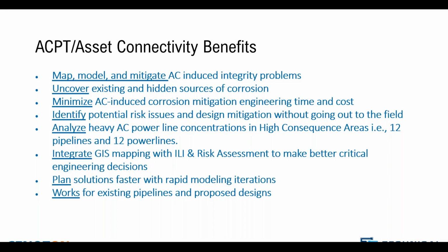The pig run is not infallible. It's fallible because we still have people looking at it, and usually the pitting that you see is small. It's not like large lengths of pitting. AC corrosion produces small leakers, and that's the problem, and it's easy to miss.